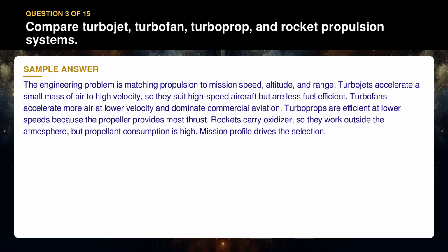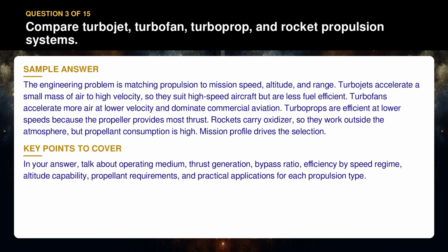Rockets carry oxidizer, so they work outside the atmosphere, but propellant consumption is high. Mission profile drives the selection. In your answer, talk about operating medium, thrust generation, bypass ratio, efficiency by speed regime, altitude capability, propellant requirements, and practical applications for each propulsion type.